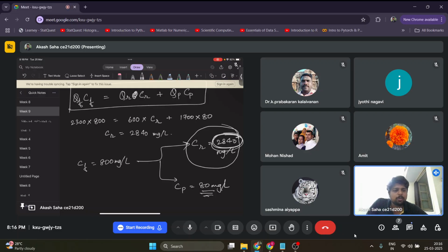Though RO is very good and the permeate quality is very good, the post-treatment investment and energy requirement is too high. The maintenance and operation required is very large, with skilled maintenance and labor needed. That is the problem with RO systems.